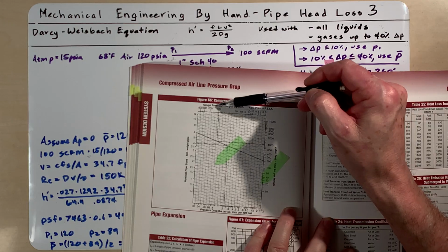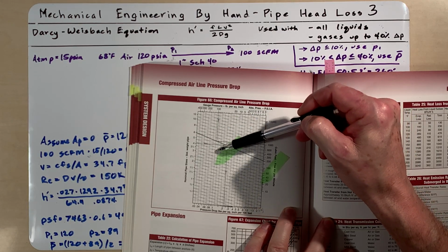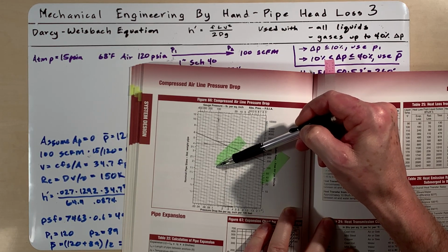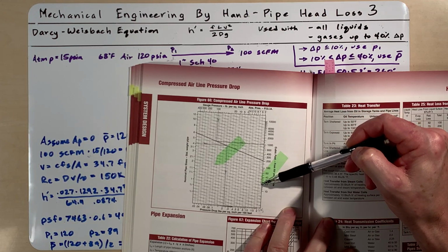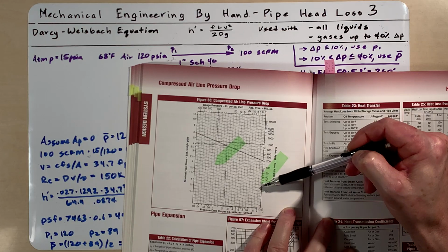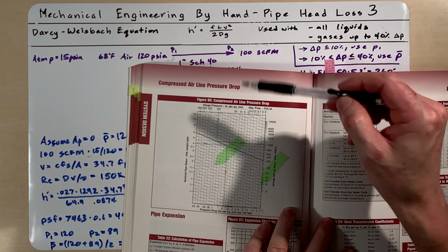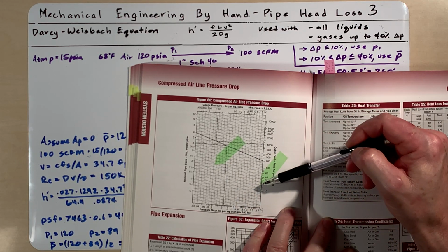They have this scale in gauge pressure here, so 105 would be right about there, and then we follow this diagonal line down to the 1-inch pipe, and you can see where I kind of got lucky. I didn't plan this out, but it just happened to be sort of on the scale. It's in the box, but there are no numbers down here, so that's a good indicator that there may be something wrong with your design if you're off the charts like this.